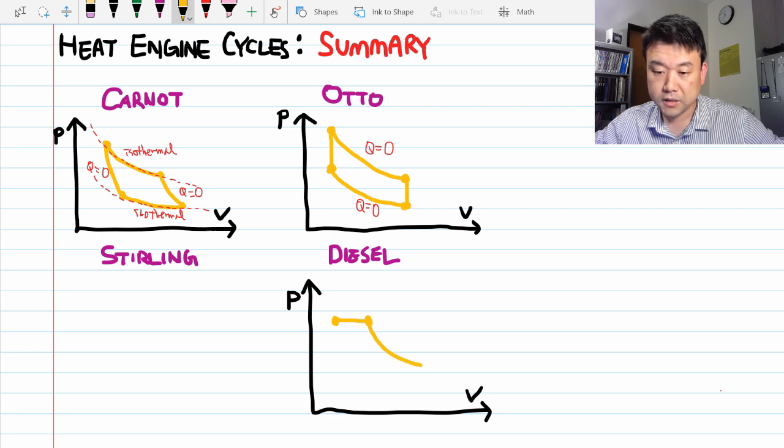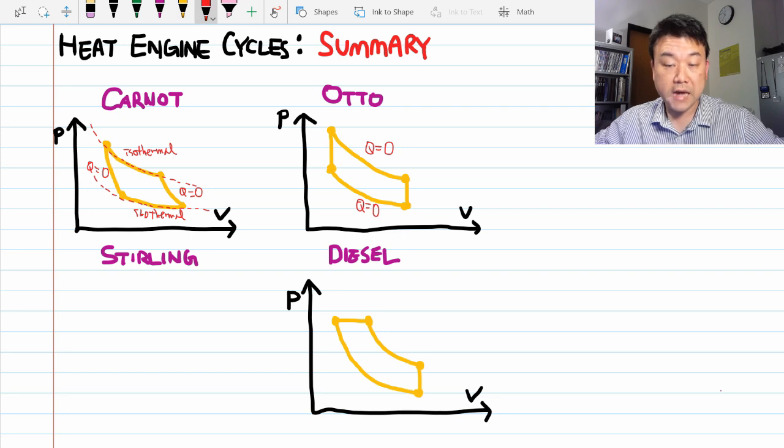And at the end of the expansion cycle, the gas undergoes cooling. We idealize it as isochoric cooling. And to return the engine to the original point, it undergoes adiabatic compression where the temperature of the air rises until it's at a point where fuel is ready to be injected, igniting all at once. The isobaric and isochoric processes are clear, and these curves are adiabatic curves.